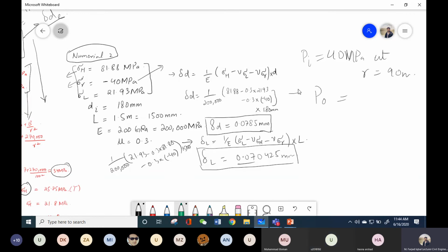Either you take the external pressure as zero, which you can do in some questions, but again, we don't have to make assumptions. It should be given in the question that the external pressure is zero, and also we have not been provided with the external radius. So it should be told in the question. That's why I'm saying that we can't do that in this question.